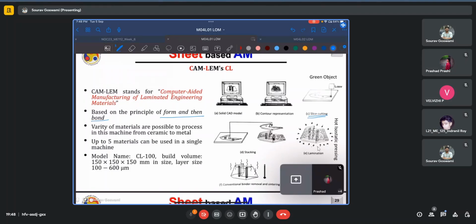Then all the cut or the formed layers are stacked on top of each other. Now in this case, you have this hollow geometry in each contour, corresponding to which maybe you can place some cylinders and use them for aligning. But if this is not the case, then aligning becomes a real challenge, and which will also determine the final finish of your part.